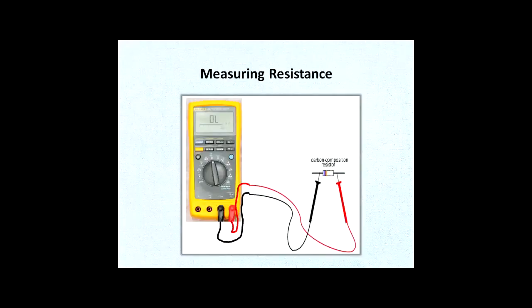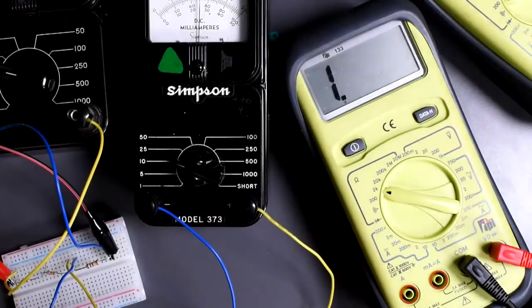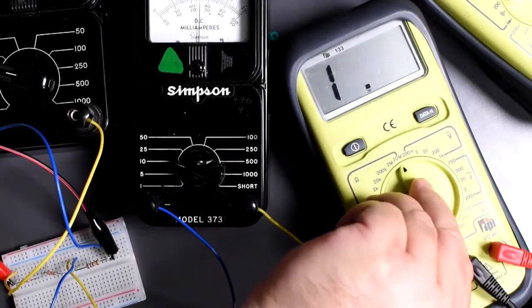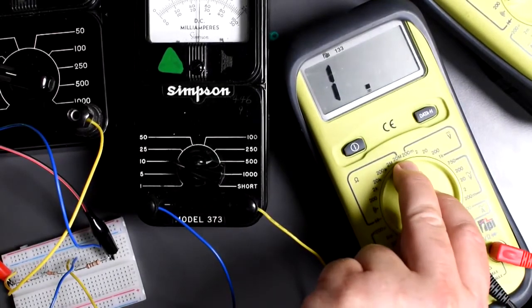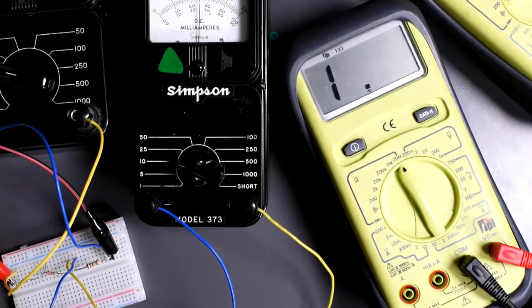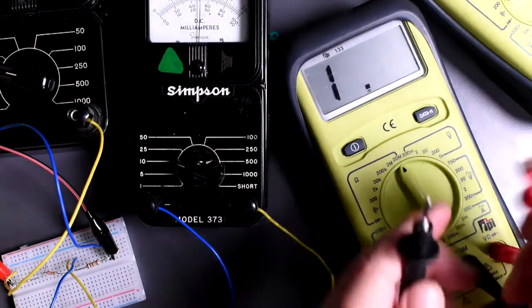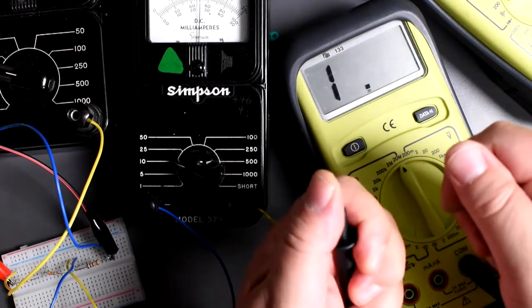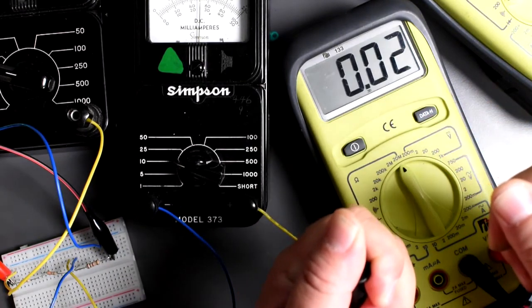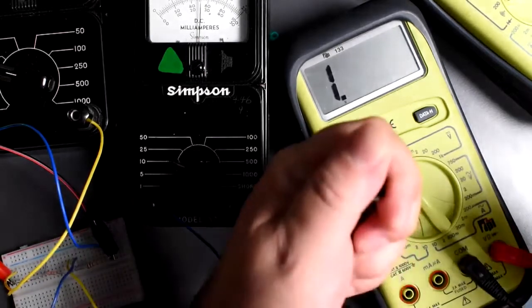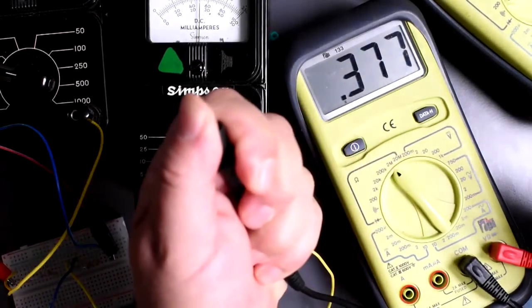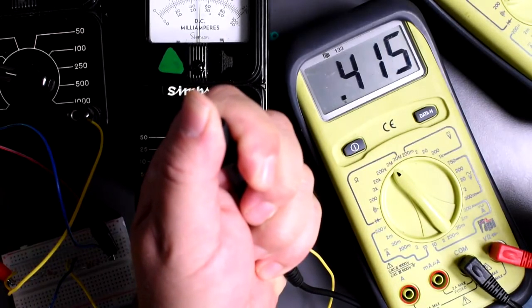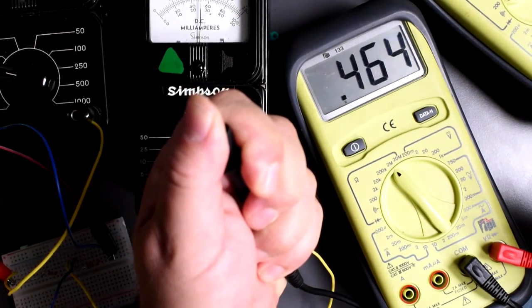Let's just see what my resistance is today. I feel pretty resistant today, don't you? Okay. Going to select the highest possible range, which is 20 mega ohms, 20 million ohms. And I'm going to hold these probes in my hands, see what my body resistance is. Oh, look at this. Well, I can even go to 2 mega ohms. All right, it shows that I'm having some resistance.